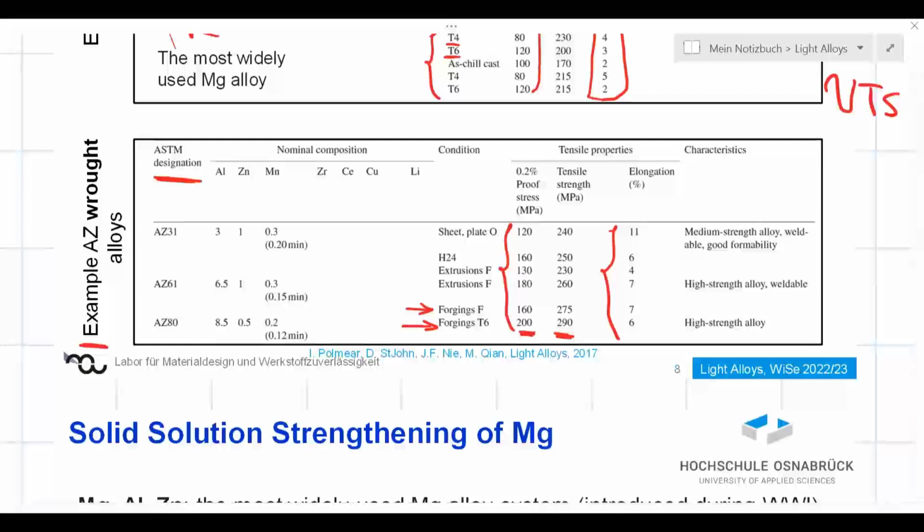If you compare them with aluminum alloy, the time in order to solidify a part out of magnesium is shorter than that of aluminum alloys. Aluminum alloys have more heat in the liquid state, and it takes longer for them to give up that heat, to transfer the heat to the metallic mold, and it takes longer for them to solidify. Whereas with magnesium, solidification times are even shorter. You could get an even higher productivity if you aim for high pressure die casting, right?